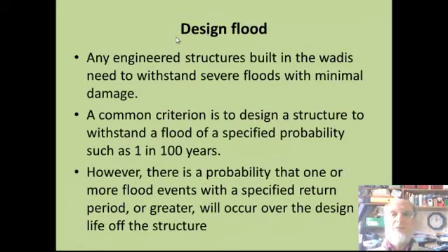We need to look at design floods, because any engineered structures built in the wadis need to withstand severe floods with minimal damage. The common criterion is to design to withstand a flood of a specified probability, such as 1 in 100 years.